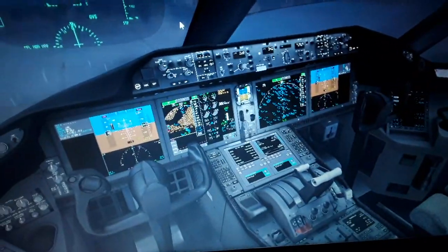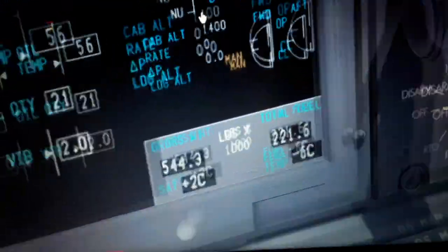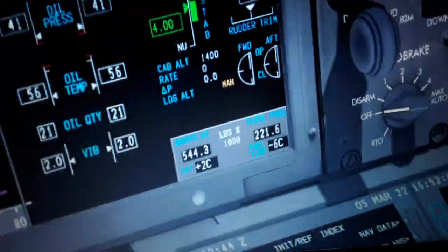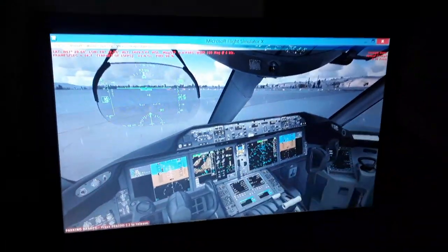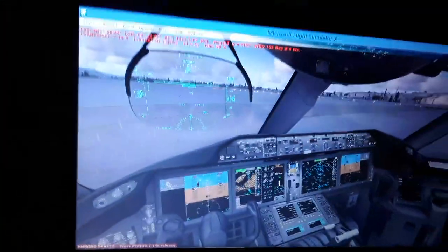I'm gonna show you all the data we need. So we have full fuel on board, 231,000 pounds. The minimum fuel temperature right now. So we're gonna see how the aircraft will behave with full fuel on board. How we can change it later. We're gonna use 30% for the left and the right wing, and 10% we're gonna decrease the fuel on board. 10% for the center tank. So we're gonna make calculations using the flight management computer over here. Gonna be calculated automatically. So I will show you also the primary flight display right now and the other functions.